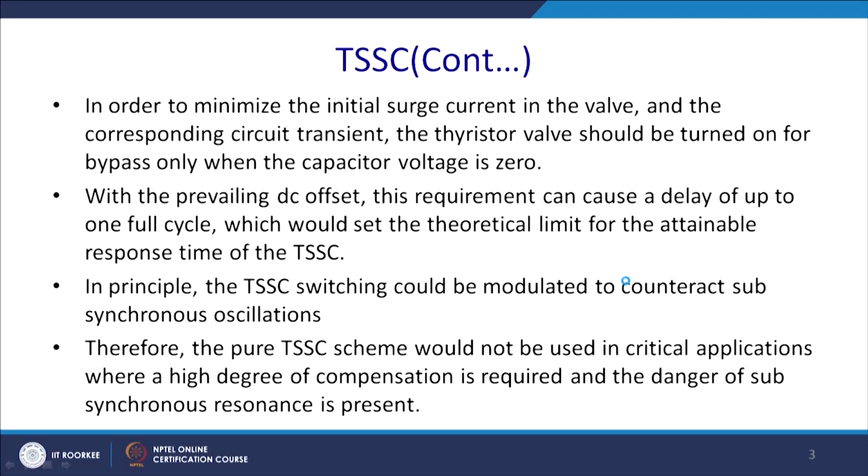The internal control technique: in order to minimize the initial surge current in the valve and the corresponding circuit transient, the thyristor valve should be turned on or bypassed only when the capacitor voltage is 0. So, we have to see that and we require to do that. How to do that?